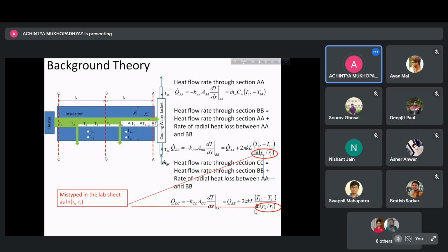In fact, the thermal resistance to the side wall is much less because the distance is much smaller. But because of the small dimension in that direction, you can neglect any temperature variation in the radial direction. That's why you considered temperature variation only along the axial direction in case of a fin.